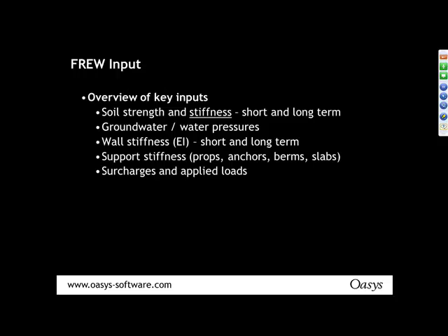What is the wall stiffness in the short and long term? And this depends on your type of wall. How about the support stiffnesses and the supports themselves? Do you have props or anchors or berms or slabs? What type of stiffnesses are acting on them? And also, are there any surcharges acting either in front or behind the wall? And what are the applied loads on the wall?